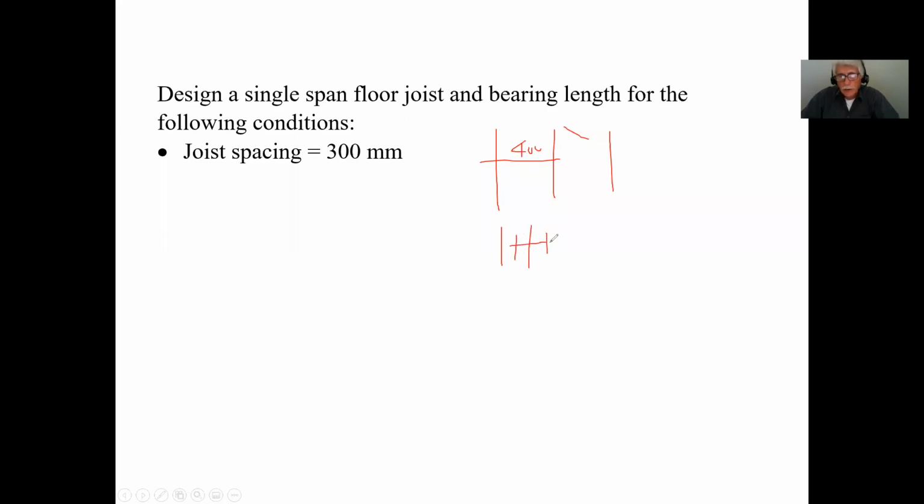And then ultimately, if that doesn't work, you might consider doubling up your joist. Anyways, all I'm saying is that for a floor, don't go over 400, and stay between 300 and 400 for the spacing for floor joists. That's the most typical spacing we have for floor joists.